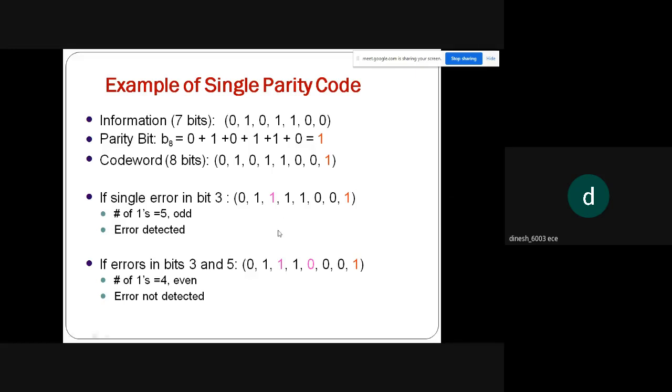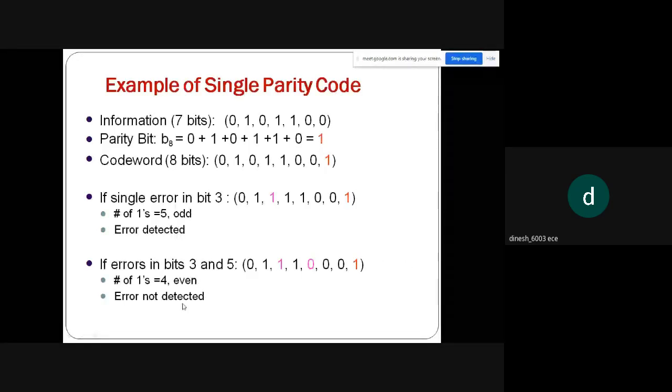It shows an error. Now, in some examples, rather than only one bit as error, if I introduce 2 bits as error, now I take the third bit and the fifth bit. 2 bits I am making as error. Then this will eventually detect 1, 2, 3, 4 only. It will detect only 4 ones. It will always be even, so the error cannot be detected at all.